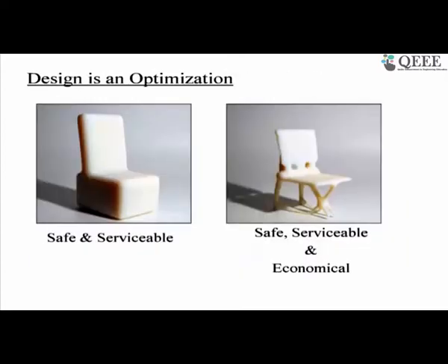Well, see, from an engineering perspective, yes, there are two limit states. One is limit state of collapse and another one is limit state of serviceability. Safety is important, it is the first priority. Structure should be safe under any circumstances. The second is the structure should be serviceable. But there is a third component in design as well, and which is economy. So we need to design a structure in such a way that it is safe, it is serviceable, and it is also economical.